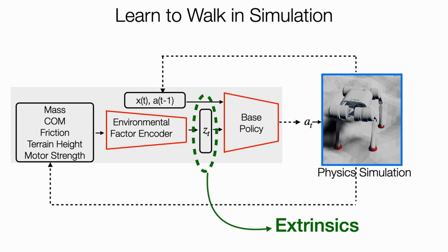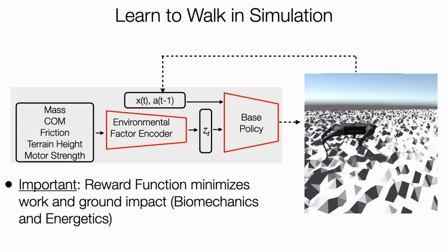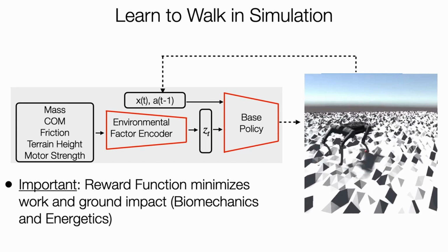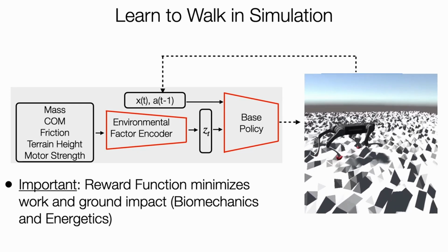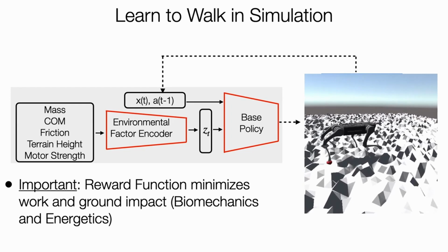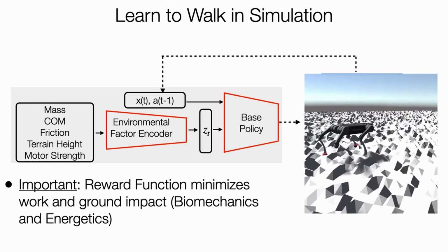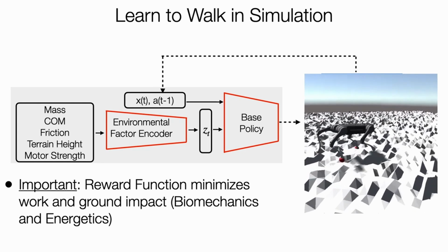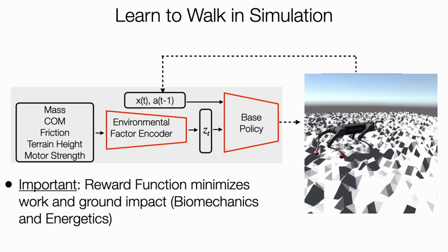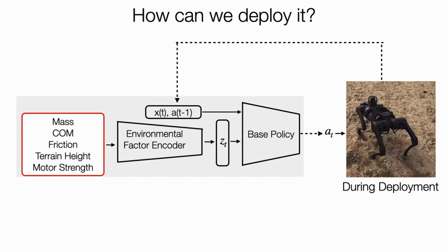Through this compressed environment vector called extrinsics, or C sub t, it holds 8 values in total. In simulation, it is going to experience many different environment configurations, and each of these corresponds to a different vector of extrinsics. They trained this end-to-end using PPO with 1.2 billion samples. PPO, or Proximal Policy Optimization, is a method for reinforcement learning. It was learned on fractal terrains from a terrain generated within the Unity environment, and this returned the OK-looking gait on the right. But when they deployed this in the real world, there is no ground truth anymore.